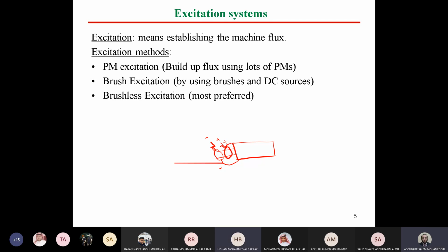However, is it going to help the motor to start or not? This is another thing. Even in the DC motor, the brushes are not for starting. Brushes in a DC motor are used to connect the armature winding. Inshallah, we will also discuss DC machines in our course and elaborate more on the operation and control of DC motors. But for now, here, brushes are used to connect the field winding, not the armature winding, because the armature windings are already on the stator side. Okay?